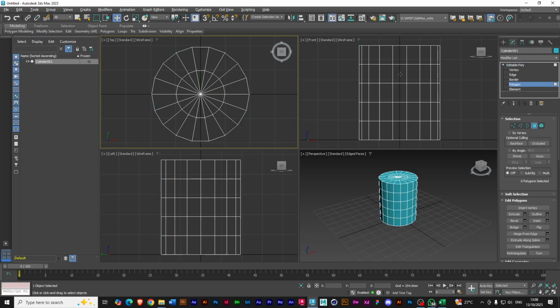I want to select this one, then hold Control and select this one. That's the trick here. To select multiple objects in 3ds Max is Control, not Shift. Polygon mode. Select those two like that. Toggle this guy, or you click on this blue one there, the one that has the name polygon. Select one face, hold Control, select the other face.